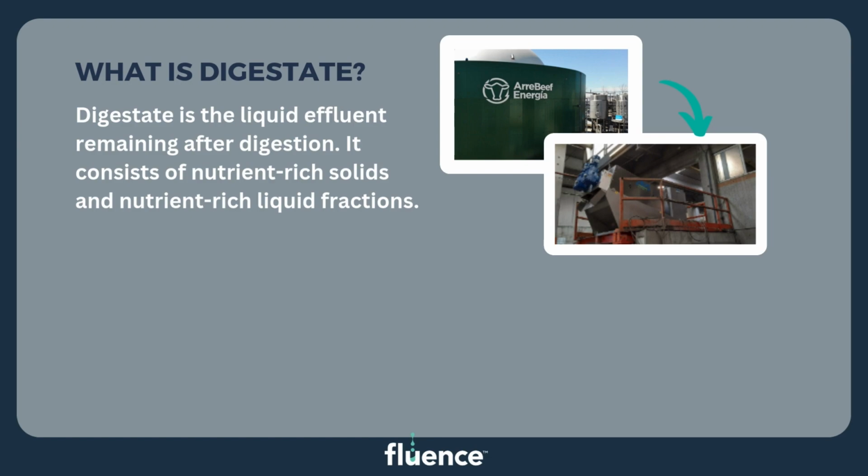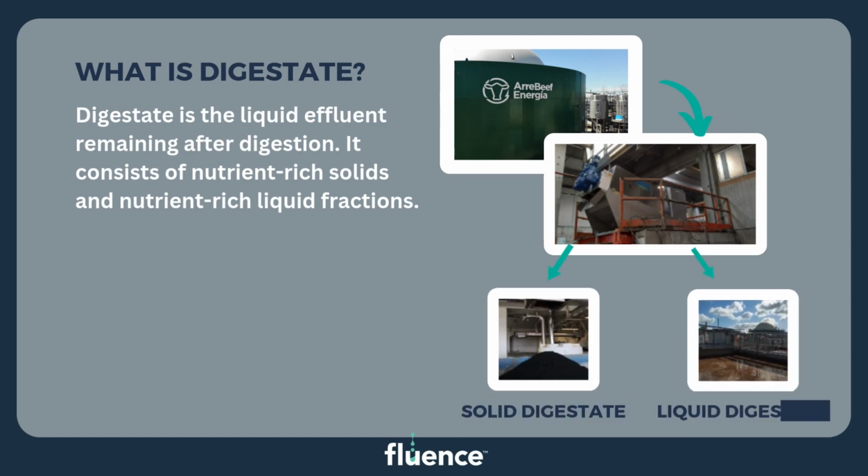We know from our Tech Talk that digesters do an excellent job at reducing the organics, but they do very little in the way of nutrient reduction. Actually, what they do is assimilate and change the form of the nutrient. So the digestate quality is going to change from project to project, but typically these systems will all have an effluent that contains a nutrient-rich solid part and a nutrient-rich liquid part. Typically in food waste and manure projects, it's possible to separate these into the solid phase and the liquid phase. This is also true for certain industrial settings, but not all industrial settings.